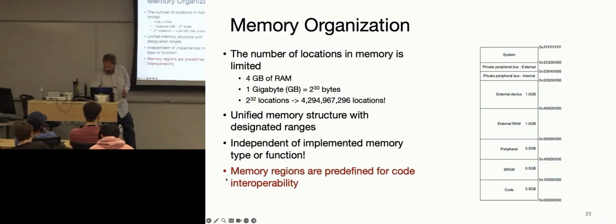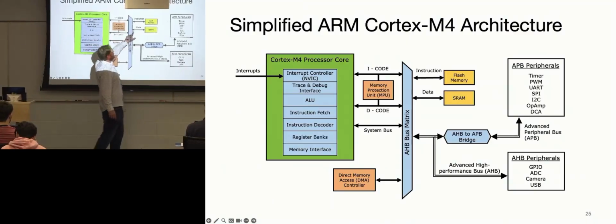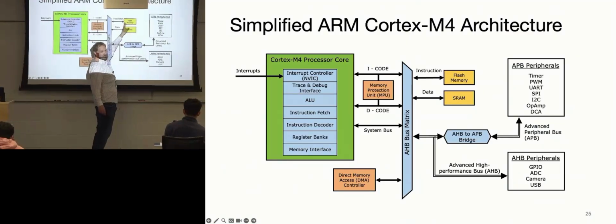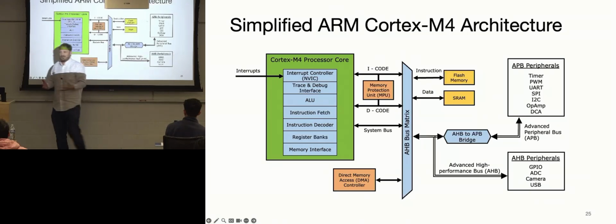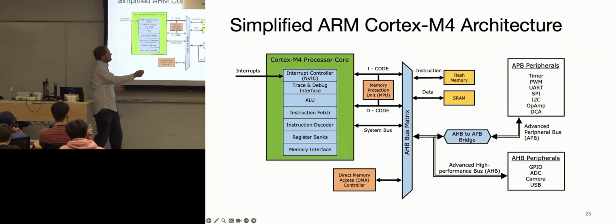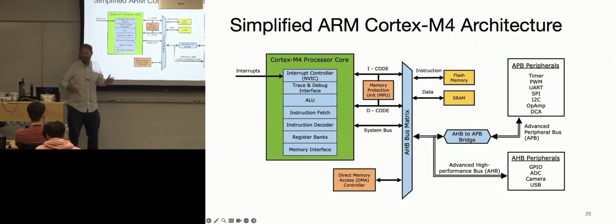Also, if you go back here, there are architectural choices underneath. There's an entirely different data bus for SRAM than for instructions. We're not going to teach you all the nitty-gritty of this processor, but there's an instruction bus specifically, and there's a data bus, and your core is optimized to fetch instructions. You don't want to mix these two up, and now your core is doing weird things. You don't want to take data and pass it to your instruction fetch and decoder logic.